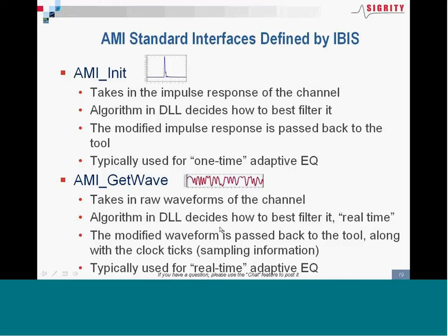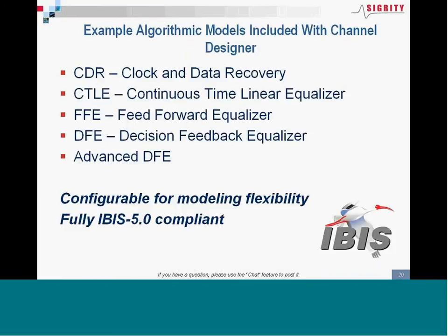And Sigrity takes a stance to be fully IBIS compliant with this. We expect to be able to easily run IBIS AMI models from any source as long as they're IBIS compliant. And this is an area in the industry where we're seeing improvements, where we saw initially some models non-compliant in the industry, but the ones that seem to be coming out now, by and large, are IBIS compliant and should be able to run in any EDA tool that supports IBIS.